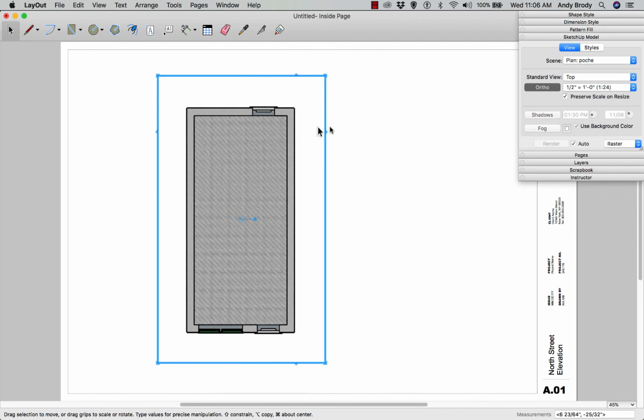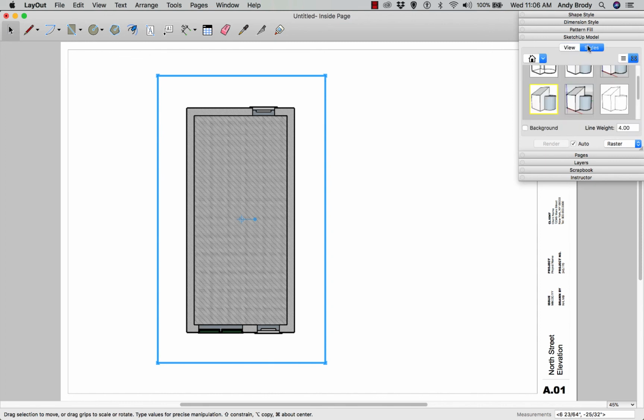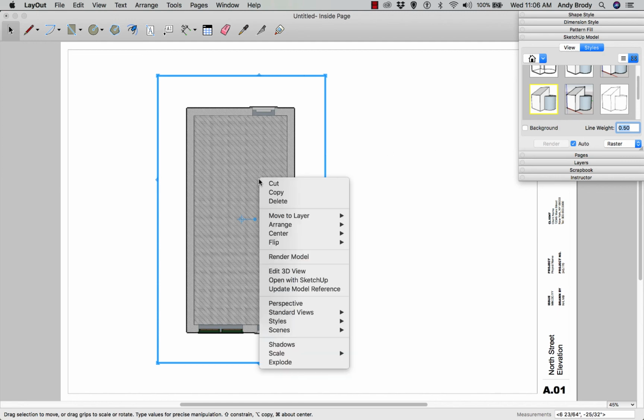And you might say, well, why do I even need to change? Couldn't I just change the line weight here? Well, what I like to do is make the line weight really light on this particular layer, so that it does not distract. Often there's detaily things like interior trim and things like that that I just don't want to see at a dark line weight. And then what I do is I right click on this layer and I send it to back.